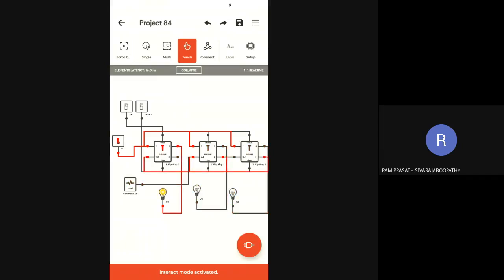For decrementing, what I told is that the normal output must be connected. That's all. What I have done is that I have given the complemented output as the clock to the next flip flop. Correct? Fine. So what I have to do is take the normal output Q and give it as the clock, and it will work as a down counter.